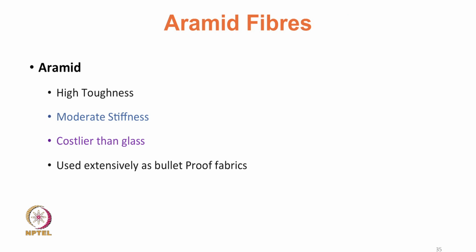Aramid fibers, Nomex or Kevlar, are used. They have superior resistance to damage, energy absorption, good in tension applications, the cable, moderate stiffness, and are more expensive than glass.